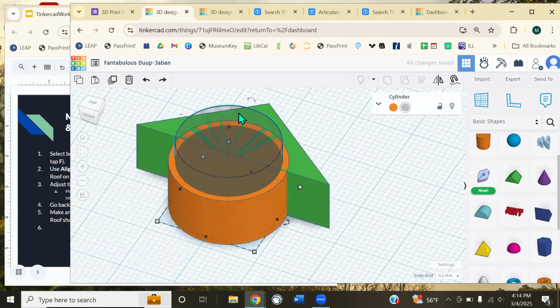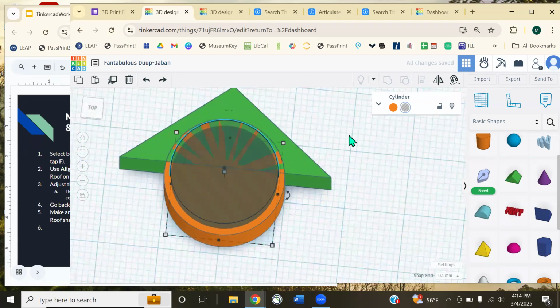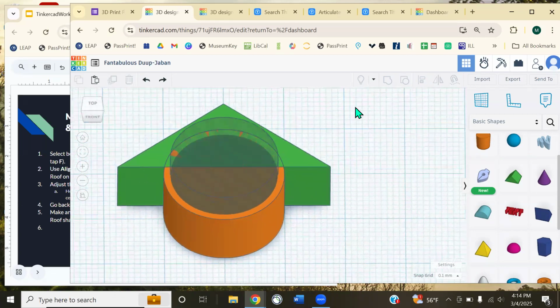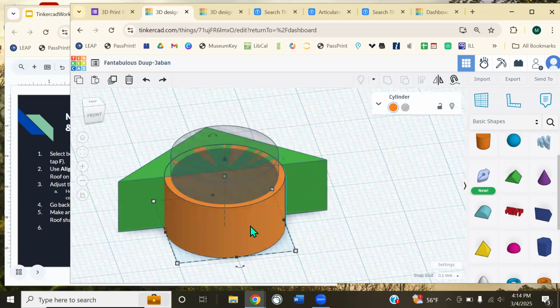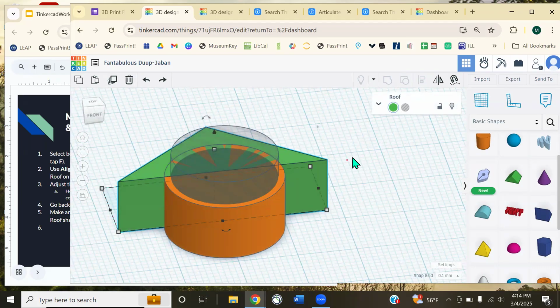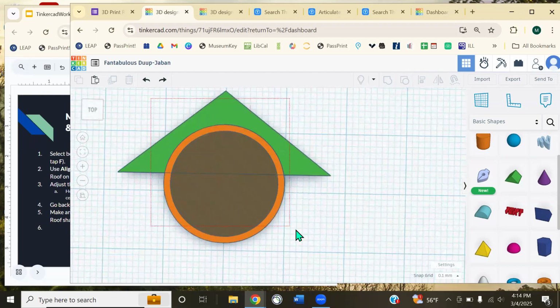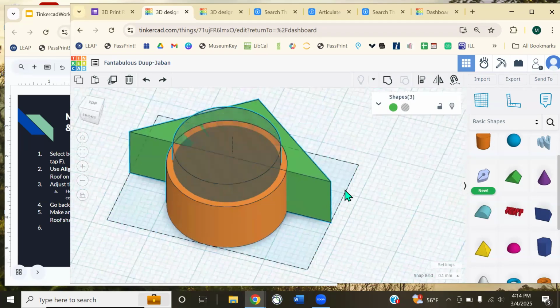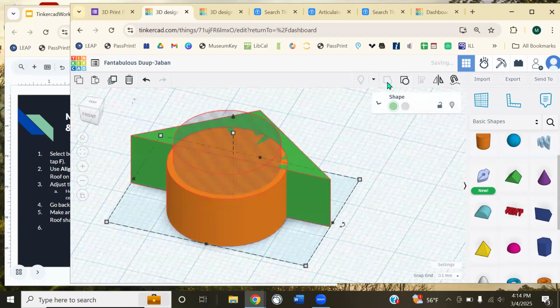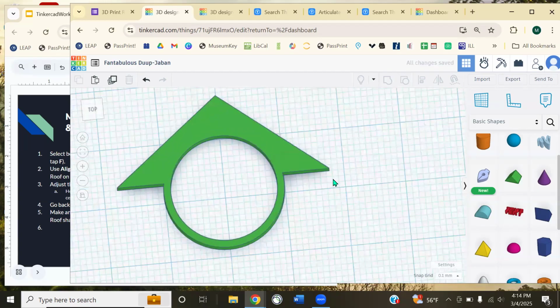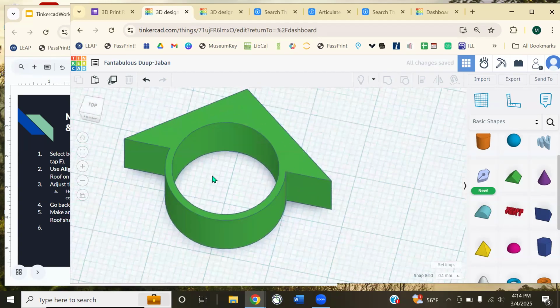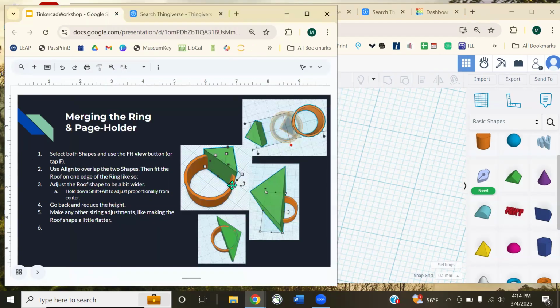And now that I have a hollow object, I can group them all at once, and then that hollow shape is going to cut out both this shape and the wedge shape at once, so I can use the same tool twice. So I can click on all of them. I'm going to use my combine tool, and then you can see we get the final shape. The stuff is cut out of the middle, and everything is lined up flush. Everything is good to go that way.